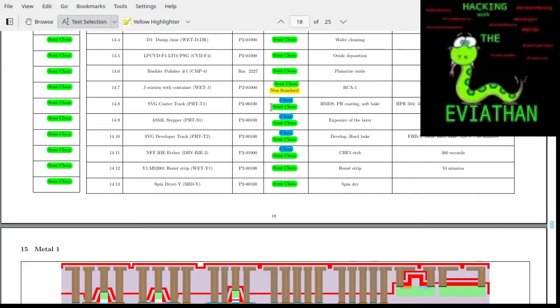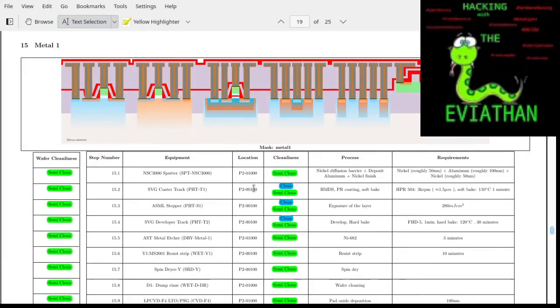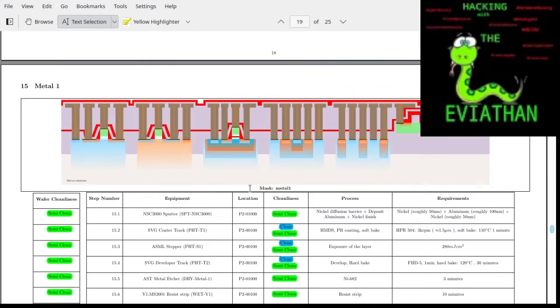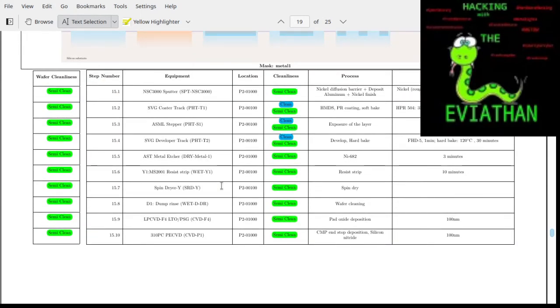depositing photoresist, exposing, developing and etching the contacts. Then in the next step, the metal layer is deposited. In our case, we were using silicide thin film layers in order to reduce the sheet resistance of our transistor junctions.